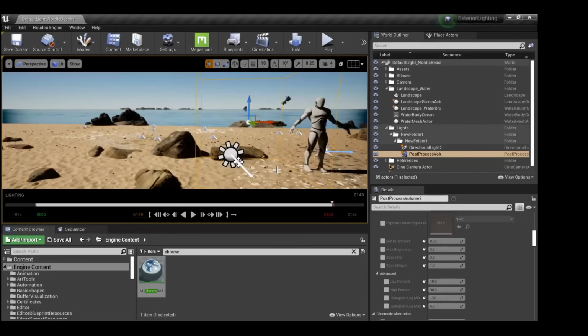Yes. So further, when we are going to use that custom HDRI, you can say that that's also a sphere, which is emitting light from the HDRI. Right. I'm not going to use this sky atmosphere. But the thing is that then I cannot control directional light and my custom HDRI without blueprint. Basically, I asked that question yesterday. Blueprint sky, every time we have to recalculate. Means you have to click that option every time you change the rotation of the directional light. That is one pain point.